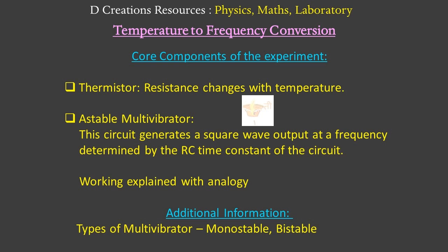So the measurement of the resistance value of the thermistor will be used for temperature measurement. Different kinds of metal oxides can be used here for creating a thermistor. It could be manganese oxide or oxides of chromium or cobalt or iron or nickel. The idea is these have to be semiconducting metal oxides.